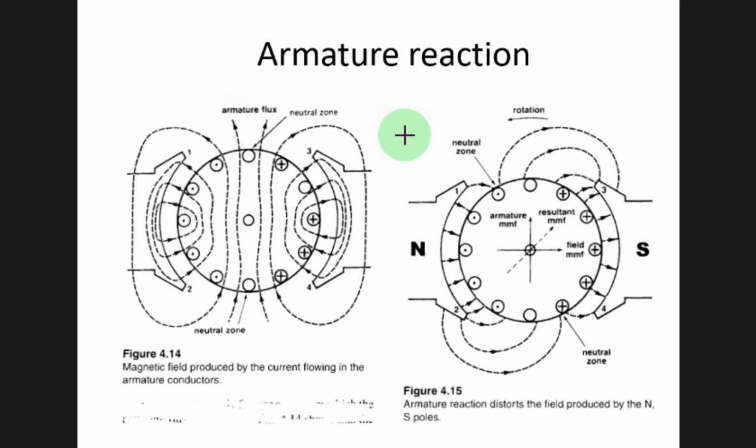But when the magnetic field is changed like this, at this point there is also a significant magnetic field, so this coil turn is generating some EMF. So at the brush there will be some sparking. The neutral zone is now moved to somewhere here, it was earlier here. This is what we call the armature reaction.